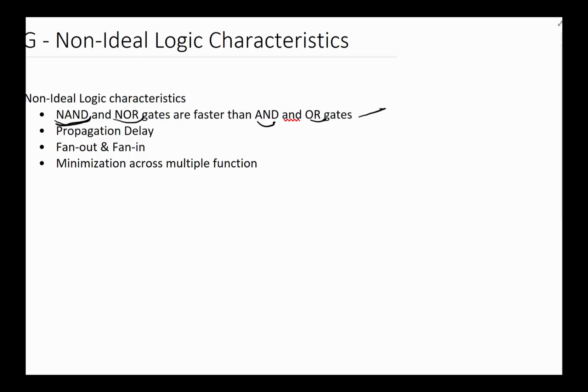The other benefit they have is that a NAND function is said to be complete, which means you can make all other gates. Imagine any gate or circuitry you want to build, and you can use NAND gates, maybe many of them, to build it. As you remember, we have done this: you can use it to build a NOT gate, you can use it to build an OR gate using De Morgan's theorem, and you can also use it to make an AND gate. So you basically can make any gate you want.